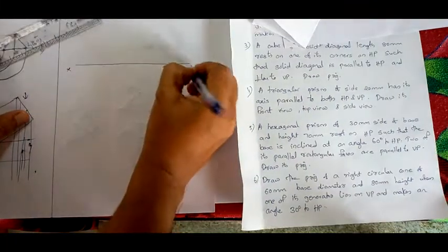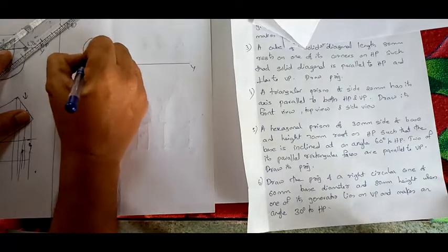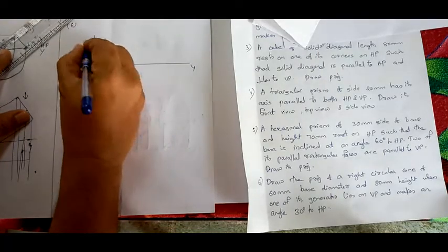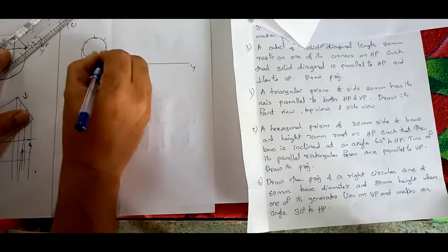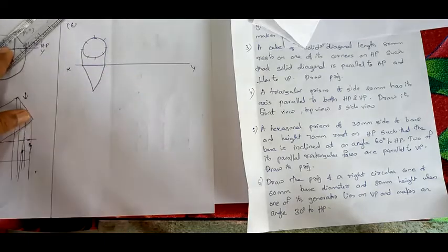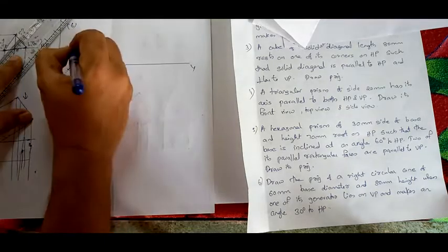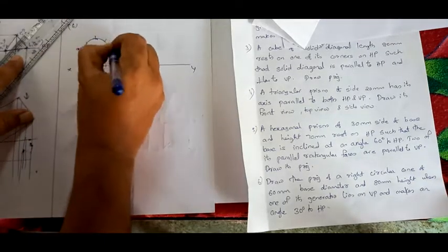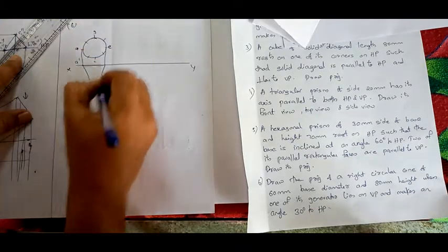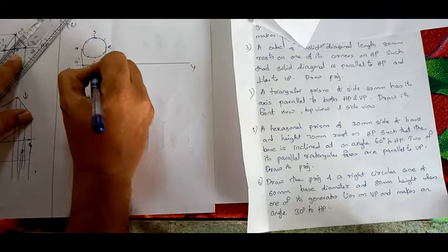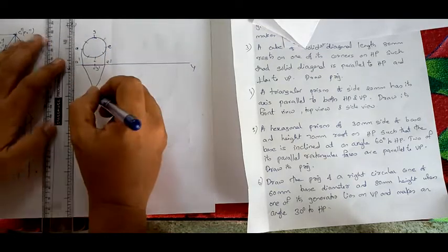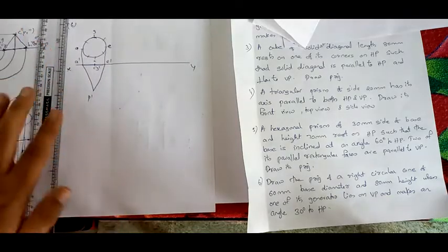Draw the XY line. VP means you can see the diameter on the front side. Now divide it into 8 equal parts, that you already know. Project it. The axis is already given, so you will obtain it like this. Here A, B, C, D, E, F, G, H. So this will be a dash, p dash, e dash, p dash, and here c dash, g dash. I am mentioning only 4 for our purpose.